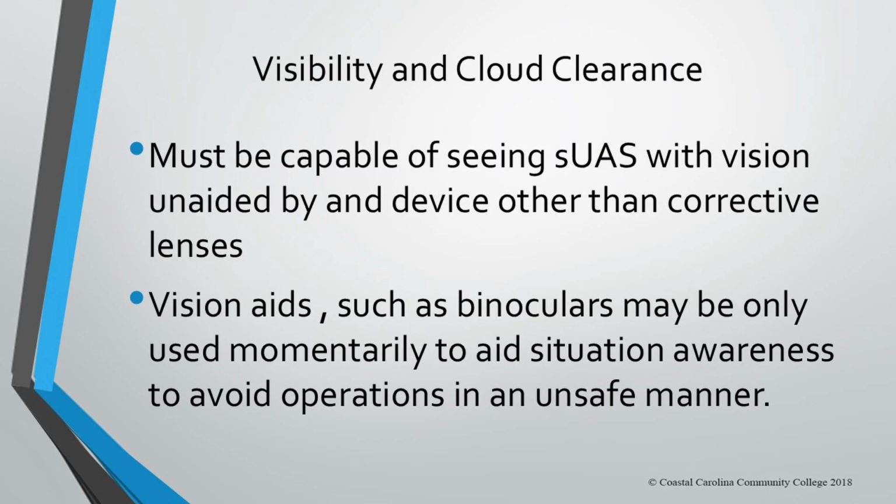You must be capable of seeing the drone with vision unaided by any device other than corrective lenses. Vision aids such as binoculars may only be used momentarily to aid situational awareness to avoid operating in an unsafe manner. So you have to have eyes on the drone.